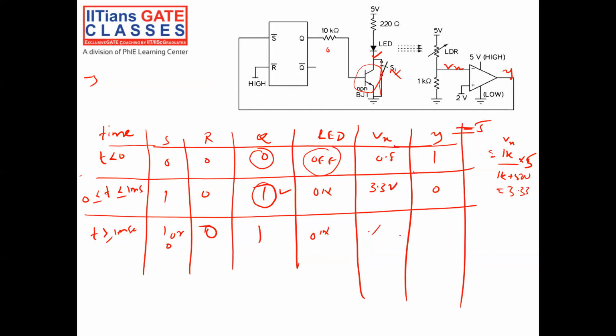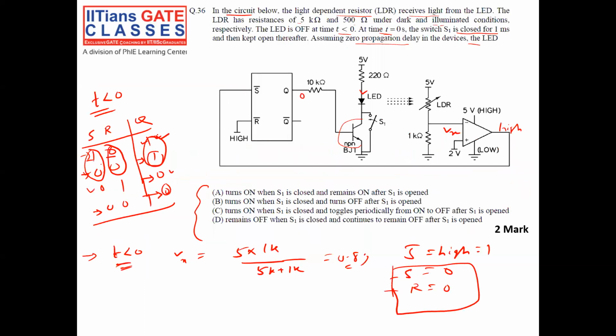No need to check any condition, because once my output goes to 1, since R is already tied to 0 and I am not changing it, whatever may be S equal to 1 or 0 doesn't matter. My output Q will remain 1.